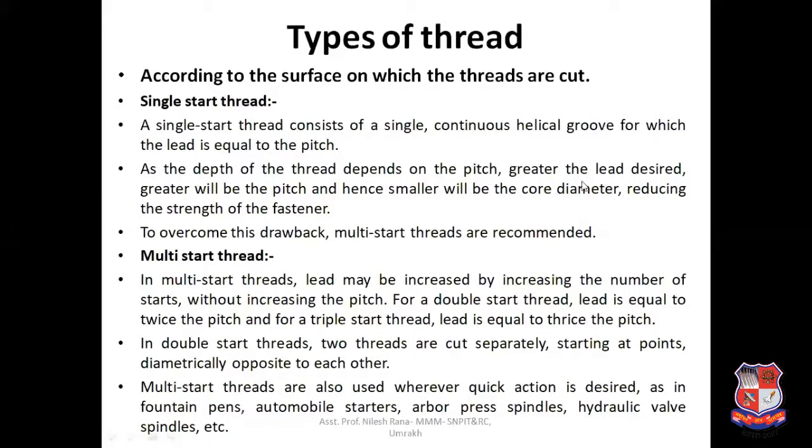And if the lead is increased, the pitch is greater, and hence the core diameter of the screw thread will decrease and become very small. At that time, it will reduce the strength of the fastener. To overcome this drawback, multiple start threads are recommended. So that's why we are using multiple start; there is a reason.